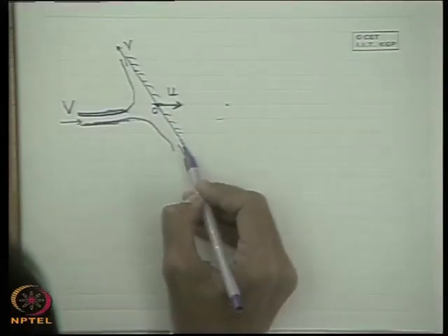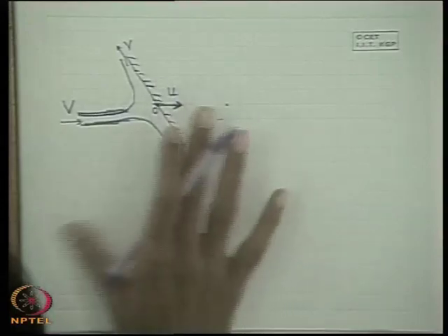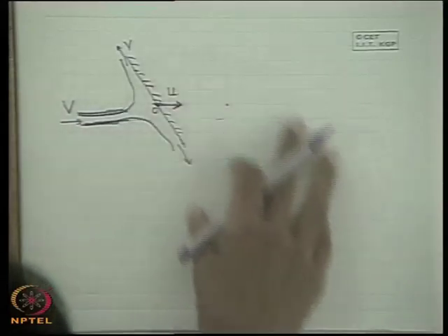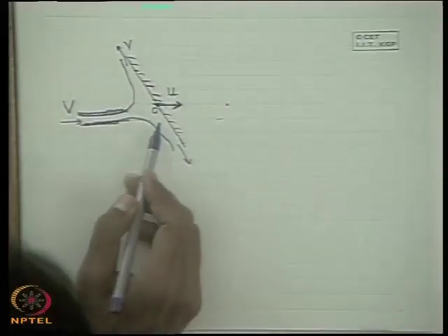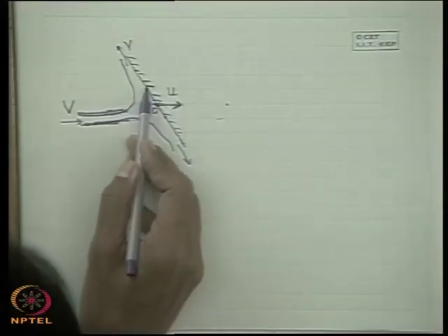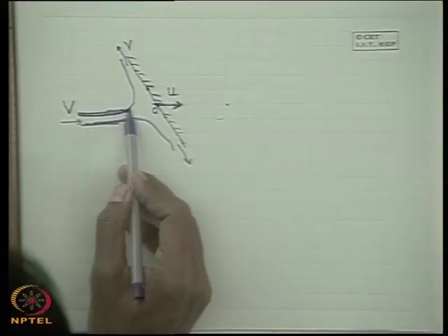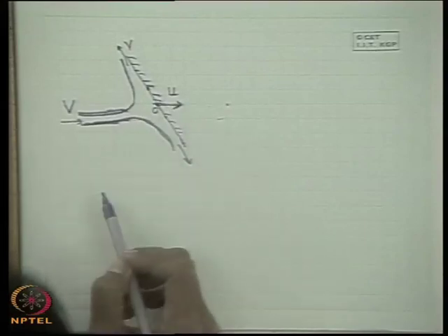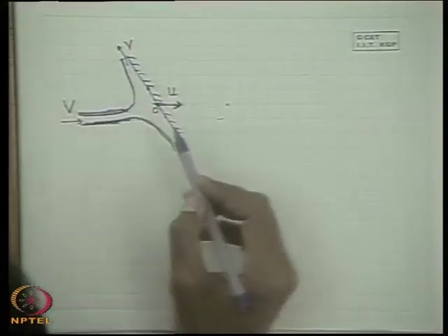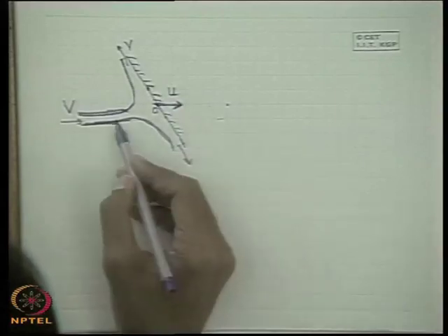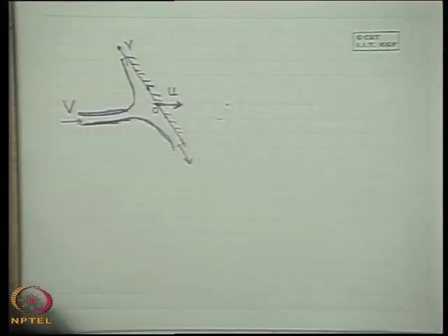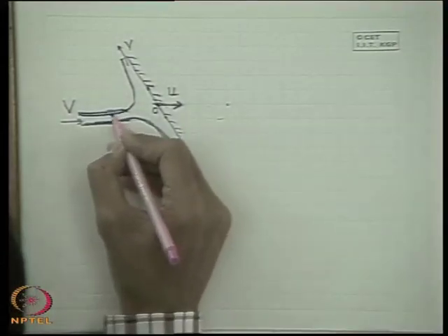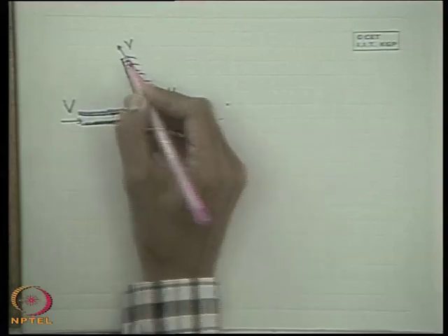But if we observe the flow, as I gave an example earlier, in a river while sitting on a moving boat or a moving steamer, the flow surrounding the boat or steamer will appear steady. Similarly, if a person observes the flow field while moving with this plate, he will always see a steady flow field in the immediate vicinity of the plate, which mathematically means that I will take a control volume and also the axis attached to the control volume which is moving with the plate. That means here comes the concept of a moving control volume.